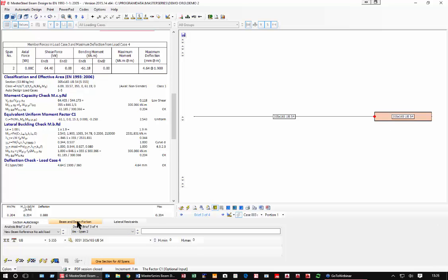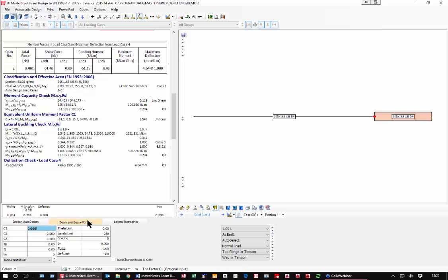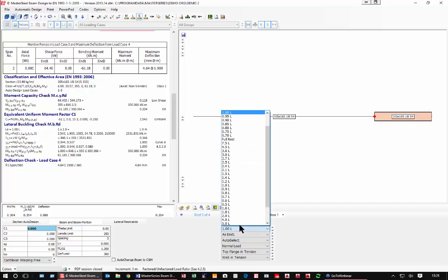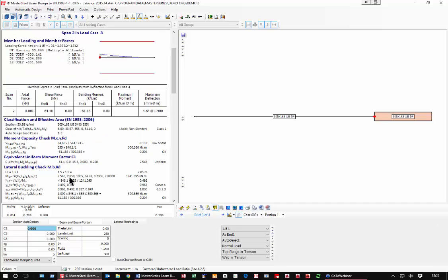If we go one stage further and say, well, this is actually a cantilever, so a cantilever with end free, and we would probably decide to come here, if it's pretty free, to at least 1.5L on the cantilever end. That's still not giving me a problem with the section size that I've chosen.